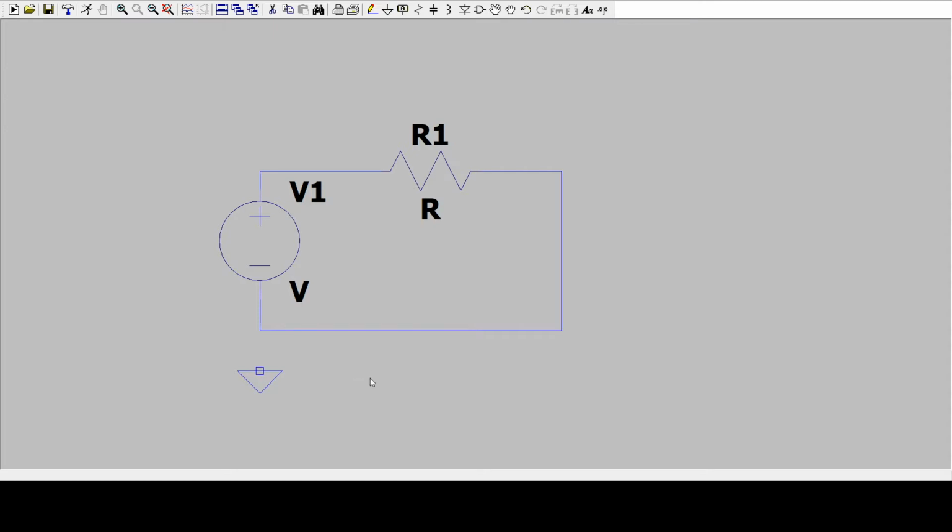And again, Mac users, you can get to that here with, I always have to find this one for me. Give me 1 second. Yes, so this one you'll have to go to label net, and then you can click ground and clicking OK. That will create a ground symbol as well. Okay, so let's wire up our ground.